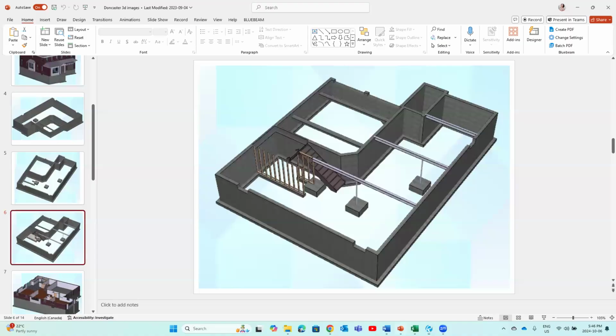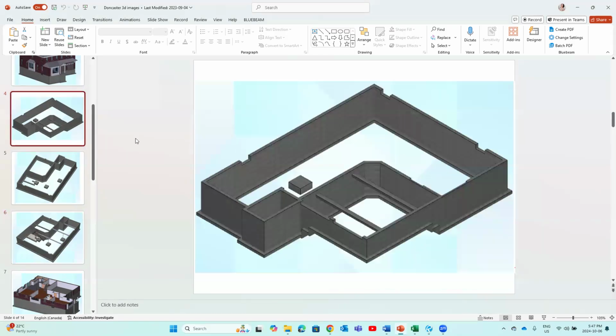If we look at the 3D drawing, we have this foundation footing, foundation wall, column footing, right? And we have a recess on top of the foundation wall for the windows and garage doors. Those are the places we need to think about from the edges. And also formwork for the slabs. We have special formwork for the step footings. The step footing goes there, right? How do we consider that?